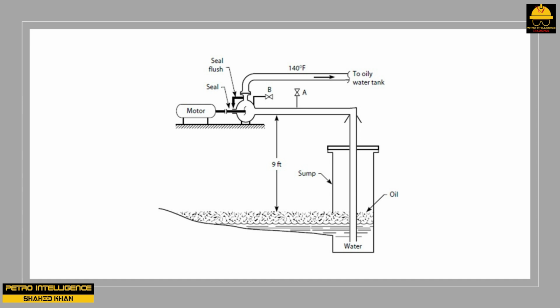One especially vulnerable area is the packing gland around the valve stem of the pump's suction valve. Another potential area of air in-leakage is around the pump's mechanical seal. Air drawn into either area will cause the pump to cavitate and lose its prime. The flow through the pump will then be lost. Playing a water hose over a leaking valve stem packing gland or over a bad seal can temporarily restore the pump to normal operation. Even better, spread grease on the leaking valve stem.